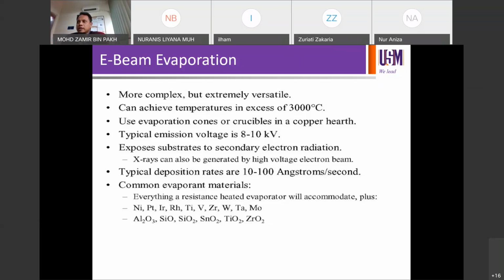I also tried silicon nitride powder on another thermal evaporation system where a higher level of current can be used, but silicon nitride still cannot be evaporated, because even though you have higher current delivered to the boat for the melting process, if the melting point is too high, what's going to happen is the high current through the material makes it jump out of your boat.